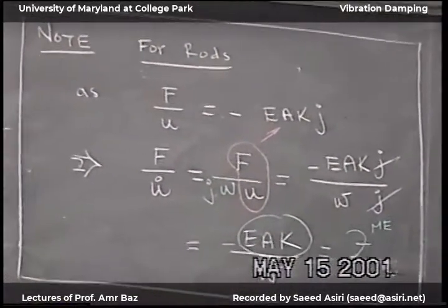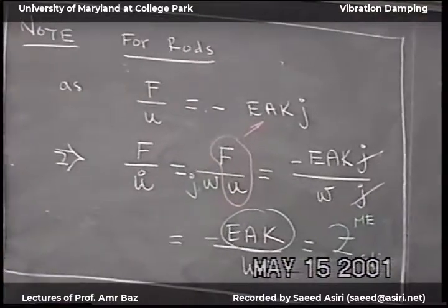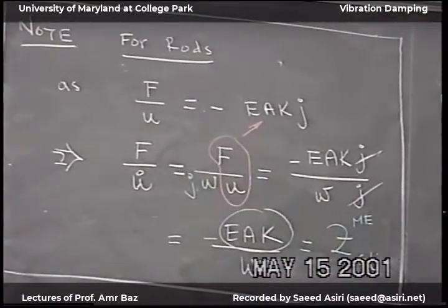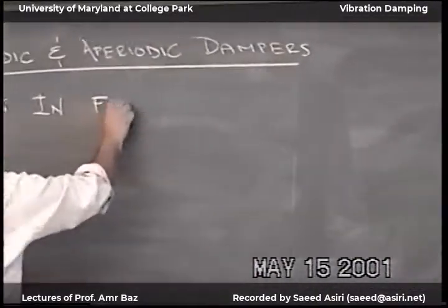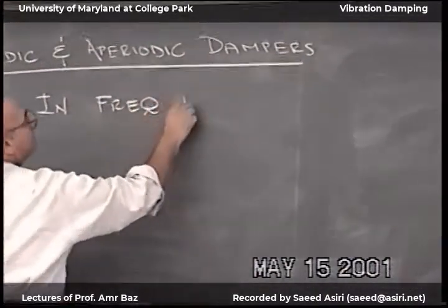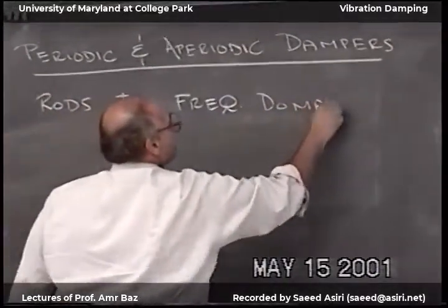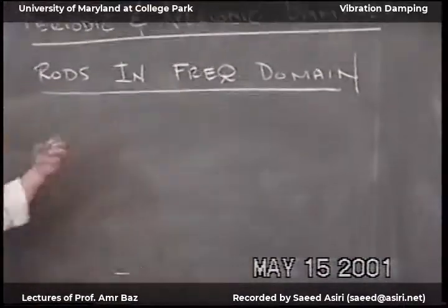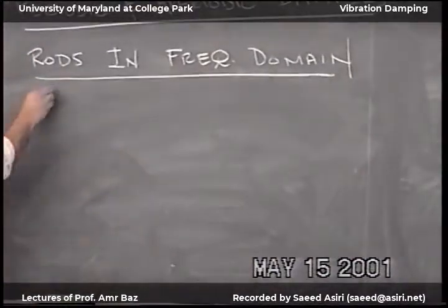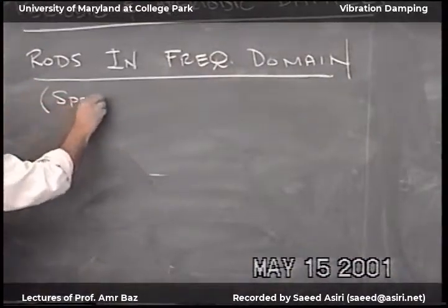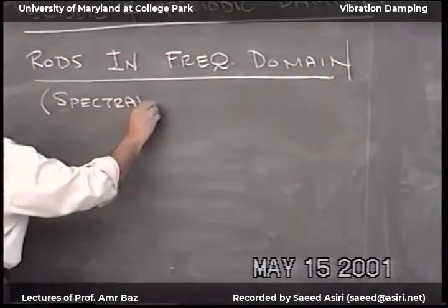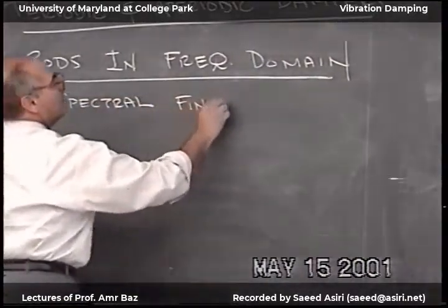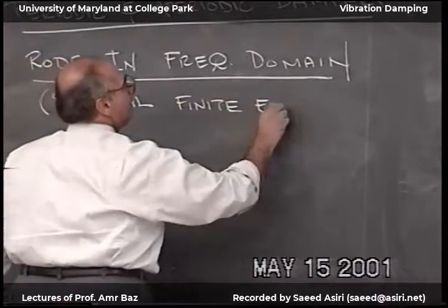And to do the rods, we will look at it in the frequency domain, and this we can translate to what's called spectral finite element.